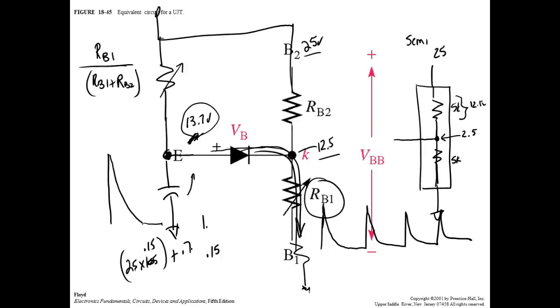But I got a forward biased diode. So you'll see this guy fire an SCR a lot, because instead of me getting a gradual voltage, it literally fires the SCR. And it'll keep firing it as long as that voltage is up there. You got to fire an SCR at least once, but it don't hurt to multiple fire it, right? So we use UJTs a lot to fire SCRs.